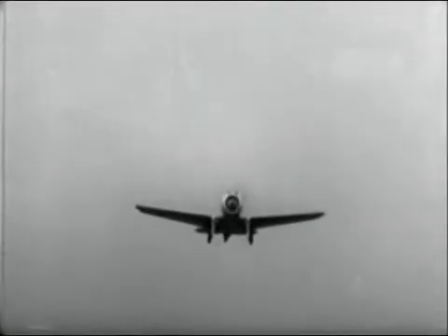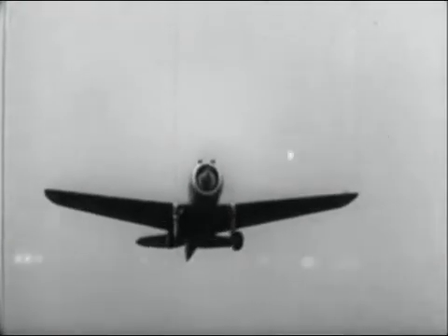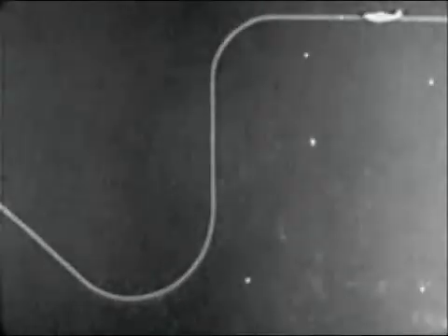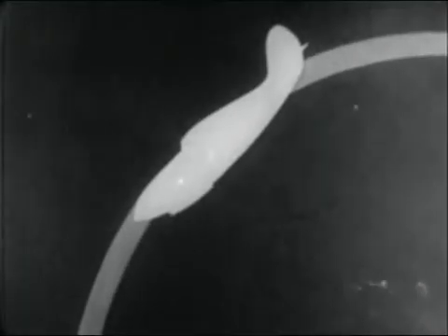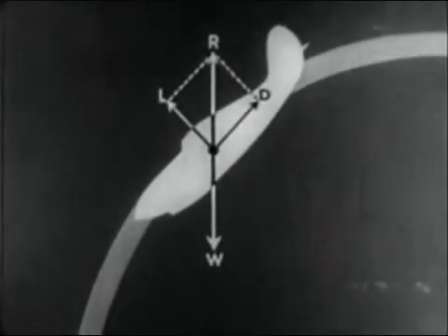Although the angle of attack is constant for any given wind tunnel test, in actual flight the angle of attack of the airfoil varies with changing attitude and speed of the airplane. Consider the case of an airplane flying horizontally at a small positive angle of attack. As the controls are set to put the airplane into a dive, the angle of attack decreases and the speed increases.